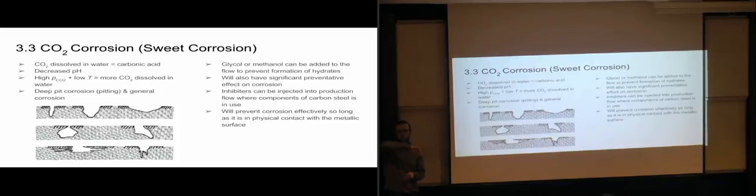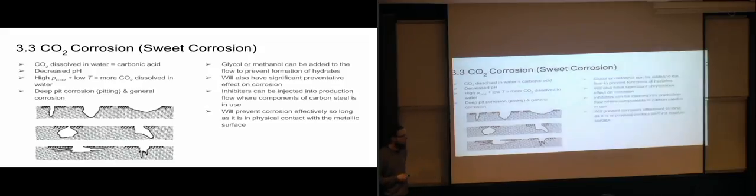It's not going to be in contact with the upper parts, but the upper part might still be attacked by corrosion. So one way of doing this is flushing your system, so that you are making sure that you're pushing through enough inhibitor fluid to cover the entire inside of the pipeline, and then you do this at regular intervals to try to refill the coating that you're getting with the inhibitors.